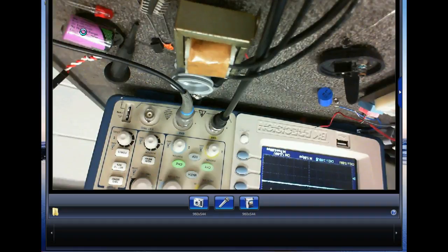So that means we'll have one big old filter capacitor on the input side, on the input rectifier, and then the output filters will be little tiny. Transformers: if we use a transformer at all, we don't have to use one. We'll just use a transformer if I need multiple voltages out. If I need one voltage out, we don't need a transformer.